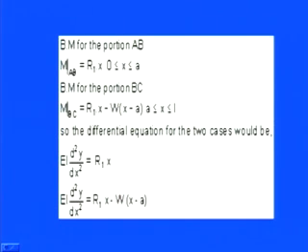So by keeping this remain, now we have this particular portion which is B to C, so W into (x minus a), and this is valid for a less than or equal to x less than or equal to L. So now you have bending moment for both of the regions. Now we need to calculate the deflection equations from the bending moment equations. So for that, again we go for the basic equation of the deflection. So we have EI d2y/dx2 equals to R1 x for AB portion, and EI d2y/dx2 equals to R1 x minus W into (x minus a) for BC region.